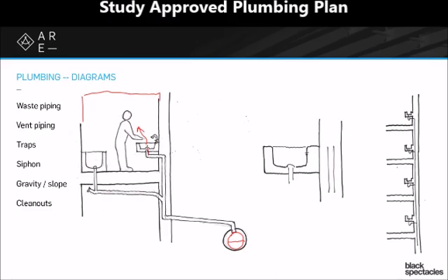Well, they came up with this very simple and clever idea, which was the trap. So instead of it going straight down, there's a little trap there. There's this little P-shaped element that creates a spot where water will fill up in the trap and create a block, essentially trapping the sewer gases from being able to get out through the sink. So that shape does something like that, where the water fills up that bottom part of the trap and therefore the sewer gases can't get past through.